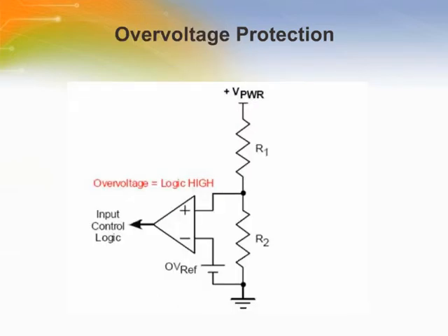An overvoltage shutdown circuit protects the power IC switch by monitoring the power supply voltage and shutting down the IC prior to the supply voltages ever reaching damaging levels. The overvoltage detection circuit usually involves a voltage reference comparator monitoring a voltage that is proportional to the voltage being sensed.